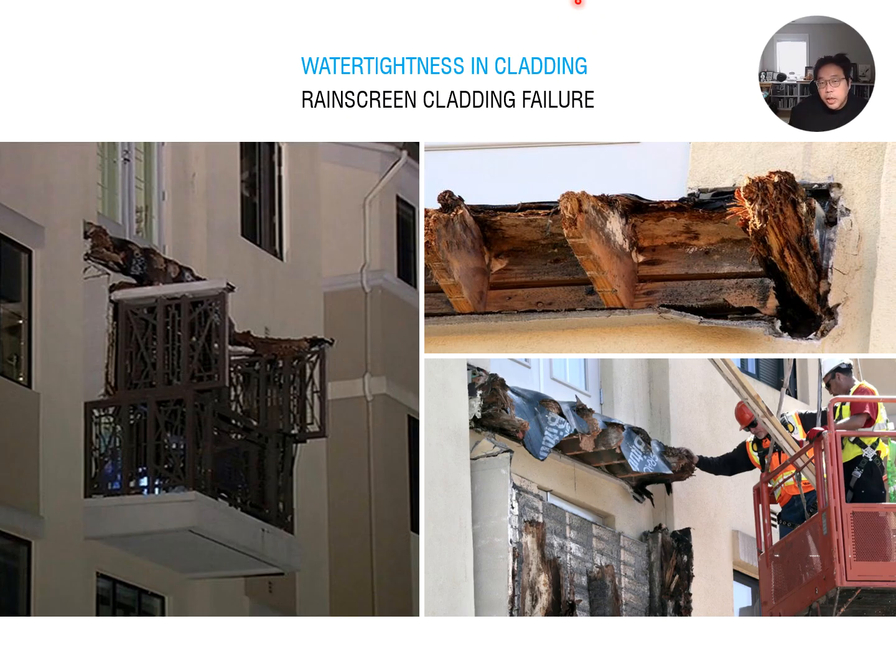As we discussed today, a properly designed rain screen system must include a cavity that allows for air movement, enabling moisture to drain and evaporate. Without this, even a well-designed aesthetic facade can conceal serious structural risk. I would like to emphasize this point.